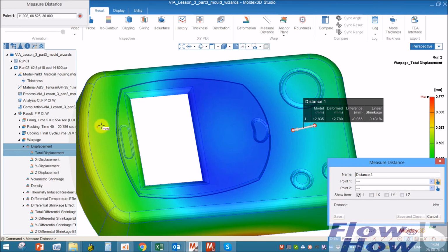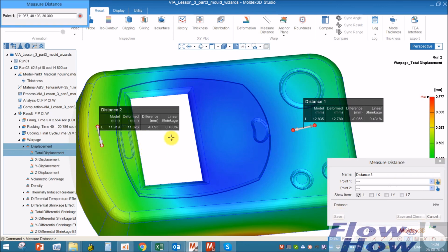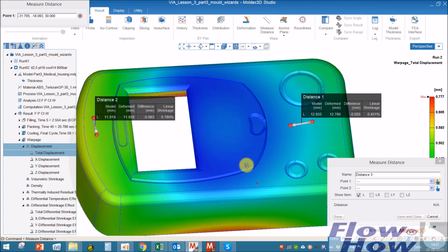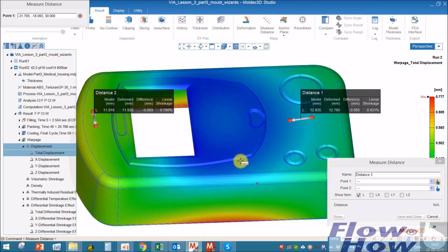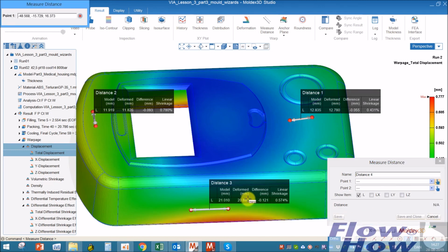But if you don't achieve one uniform shrinkage in your plastic part because the design of the plastic part is wrong, then you get bad quality, or parts out with high warpage. But this is a way to measure the shrinkage around the part, and if you had uniform shrinkage all over, you would not have any problems in the warpage.